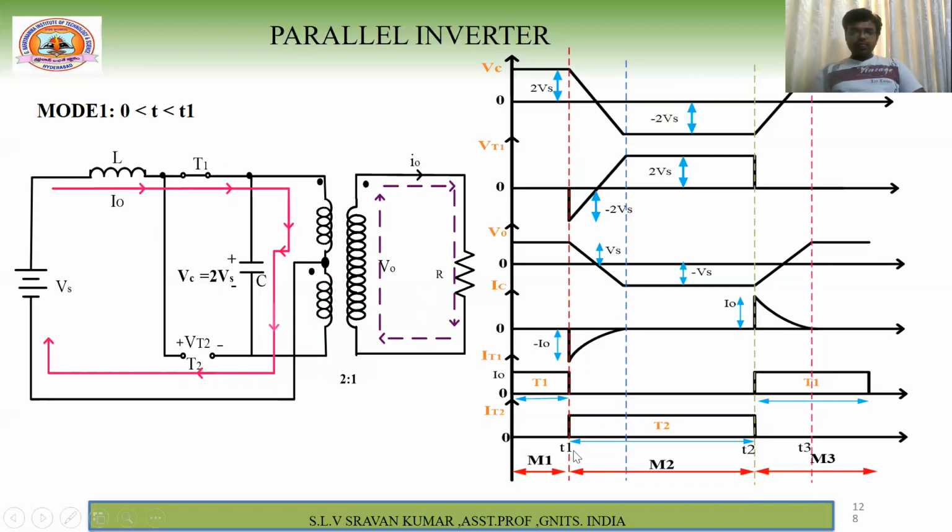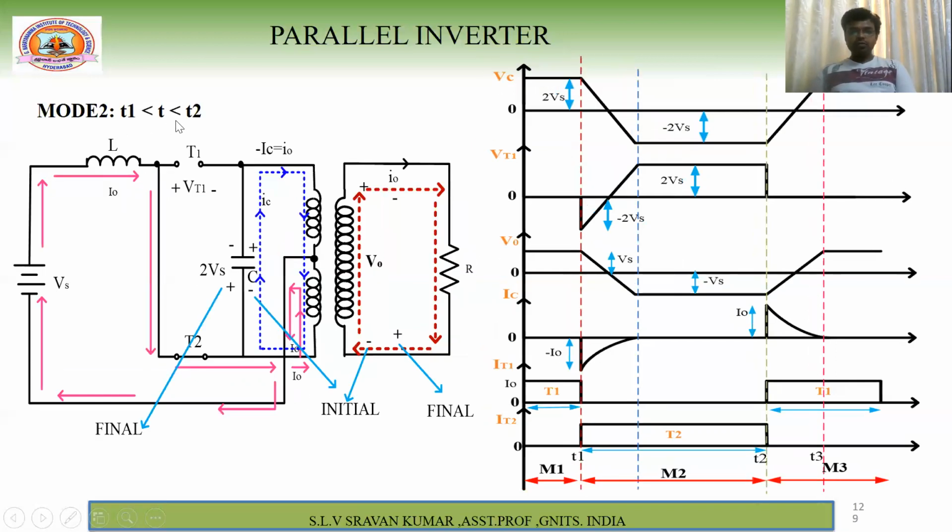Okay. So now at this instant T1, what happens? I will give the triggering pulse to thyristor T2, because this negative is applied to the cathode and positive to the anode. So these polarities favor your thyristor T2. Then I give the triggering pulse to thyristor T2 here. Now we'll see from T1 to T2. I have given the triggering pulse like this. Immediately a sharp rise of reverse current flows in this fashion. Then immediately T1 will be turned off.